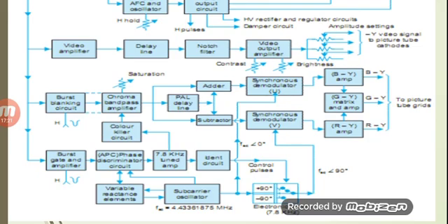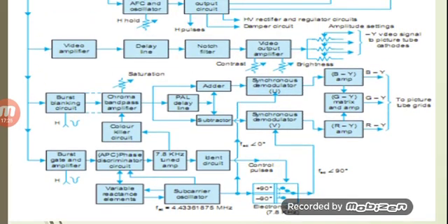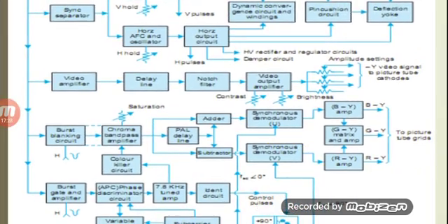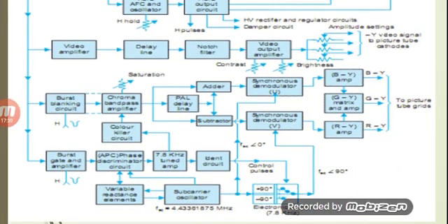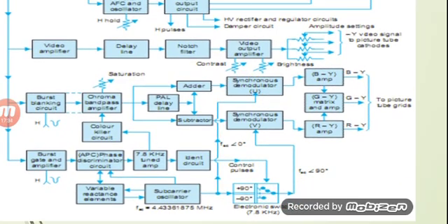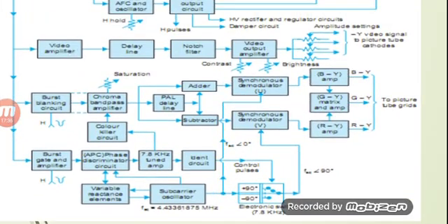Now once this line by line switch is used, it will be giving input to this regulator. For V it will be plus or minus 90 degrees, and for U it will remain unchanged, that whatever the carrier signal is there, it will be given as it is, so that from the output of both the demodulators we will be getting signal U and signal V.